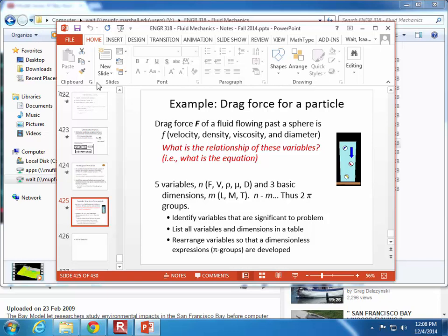We've got discharge, angular speed, diameter cubed. So that has units of cubic meters per second for the discharge. That's the units of flow rate. The units of angular speed is seconds to the -1 power, and then diameter is meters cubed. So the seconds multiplied by seconds to the -1 cancels out immediately, and then we've got meters cubed divided by meters cubed, so it is unitless.